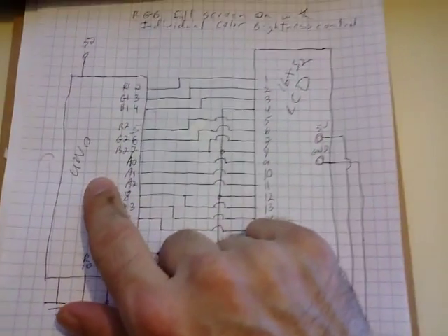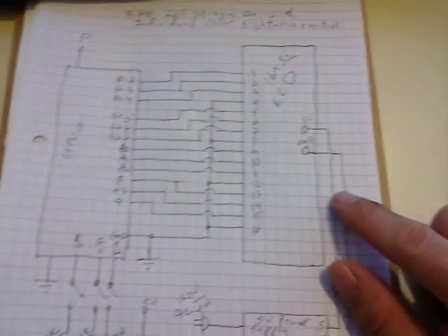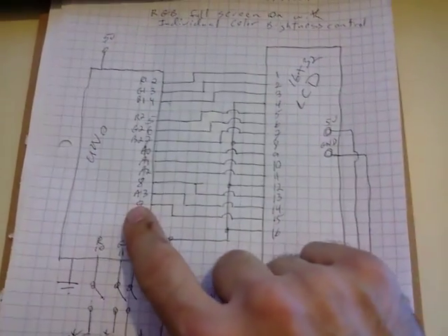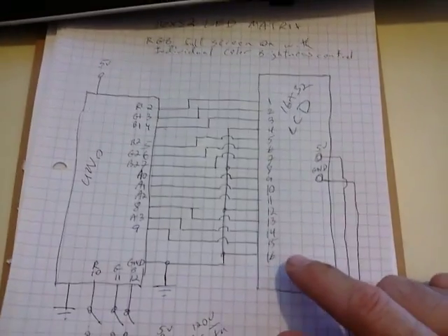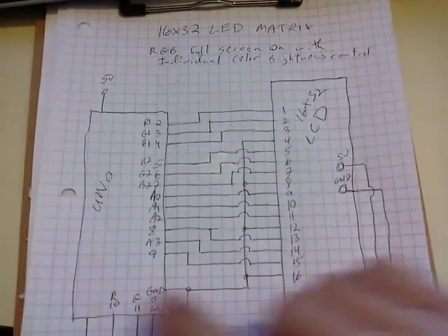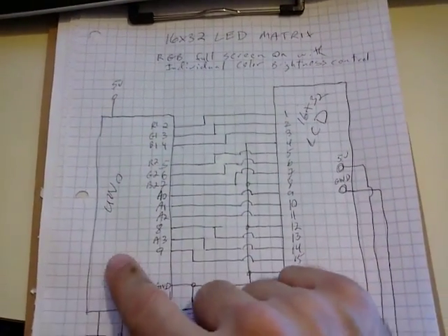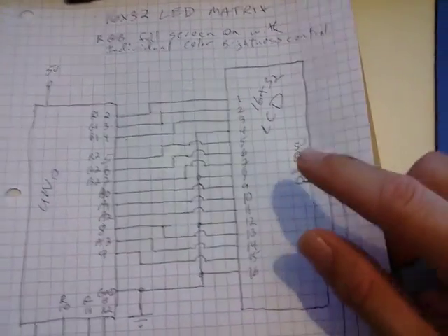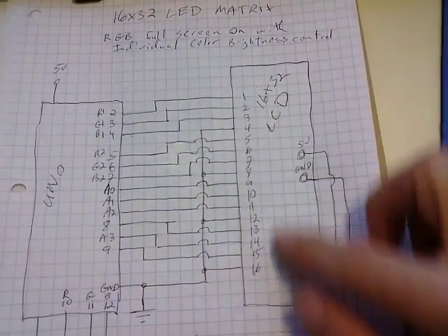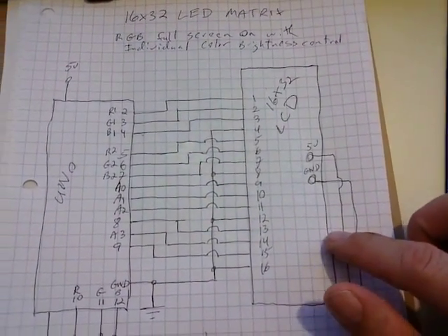Power supply is important here. Can I use the Arduino UNO? Not even close, not even in the ballpark. It doesn't have the power to transfer any voltage, no matter what voltage you input here. It cannot power the LED matrix.